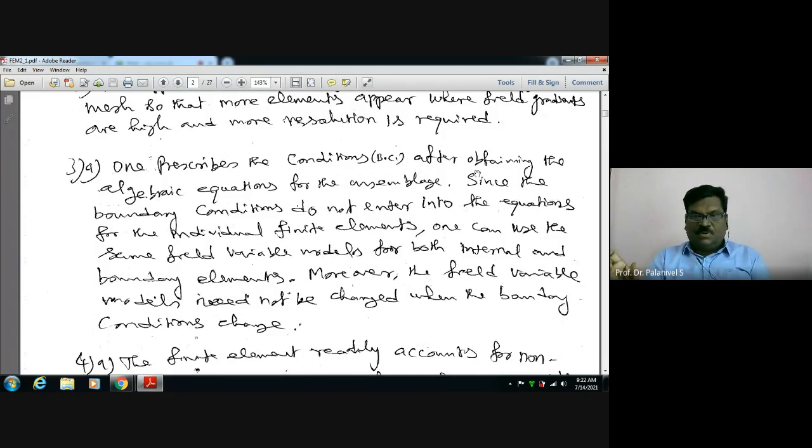Suppose you deal with a body supported somewhere, for example a beam supported at the end. You modeled it. Suppose I bring one end support inside, I am moving the boundary condition, making it a one-side overhanging beam.